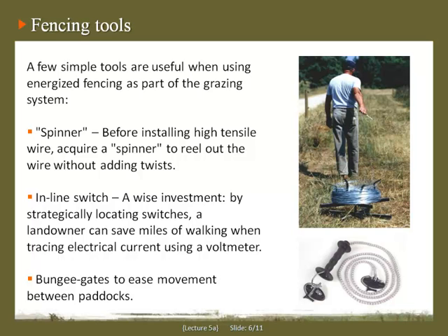Inline switches are also wise investments to locate faults in fenced areas. By strategically locating switches, a landowner can save miles of walking when tracing electrical current using a voltmeter. Bungee gates are also easy to set up and make moving between paddocks much easier.